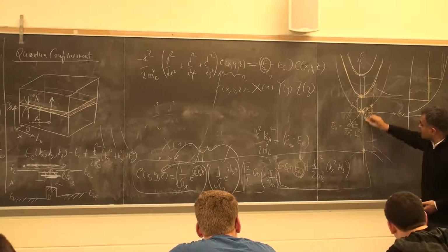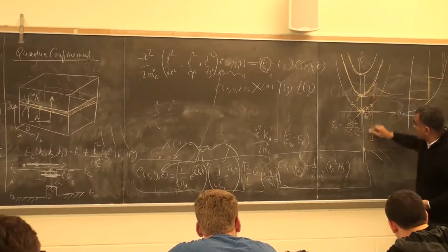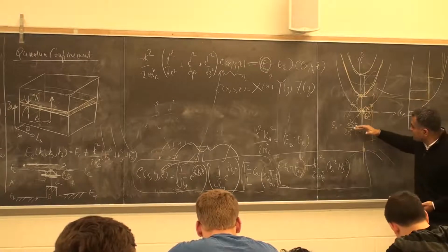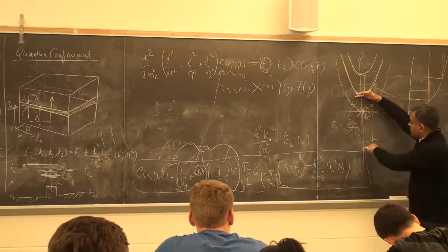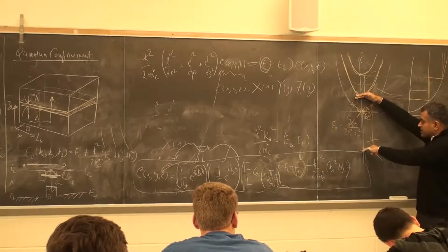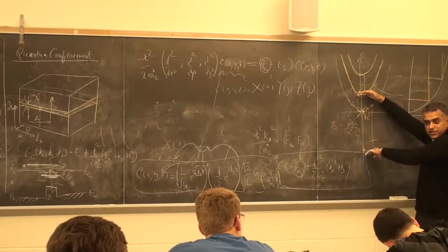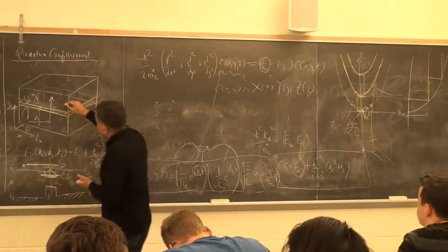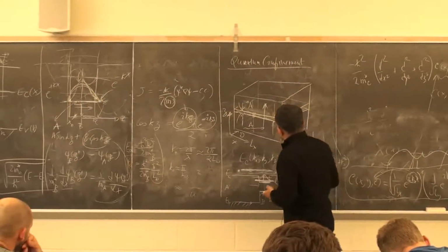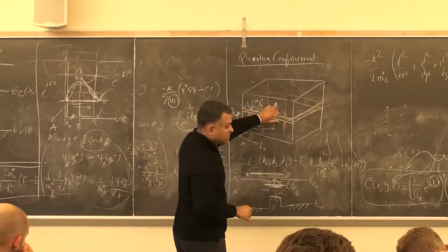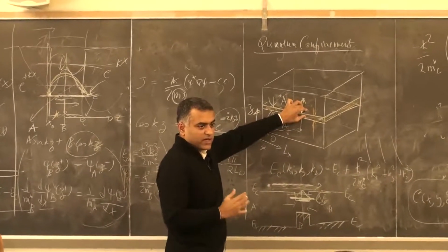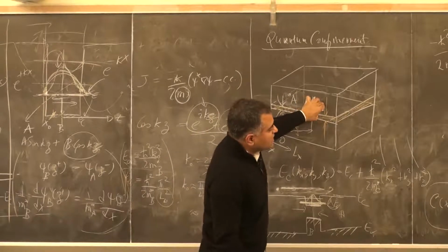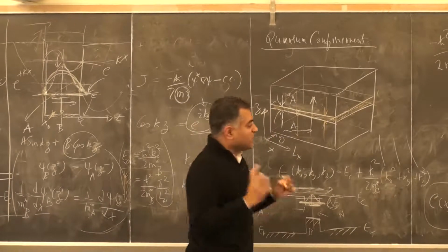So this is your artificial band gap now. If you are going to put electrons in here and holes in here, and they recombine to give you a photon, then the energy or the color of that light would be exactly determined by the quantum confinement now. So you can design the color by changing the quantum well thickness. You can go blue or red by making it thinner or fatter. Okay, so we'll have a demo of this now.